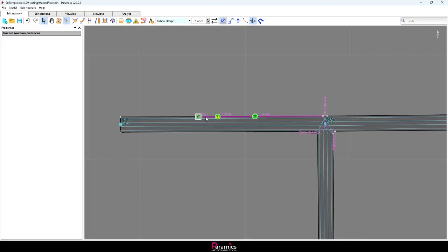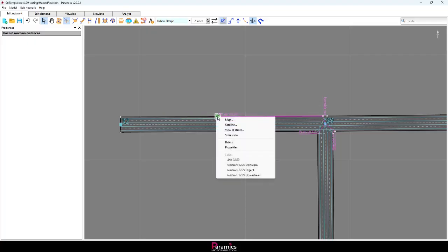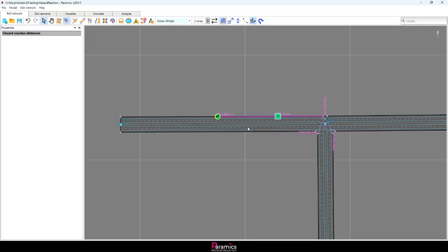This can lead to issues if they become overlapped. It may be confusing that when you pick the icon, it's unable to move. It will move in one direction, but not necessarily both. If they are overlapped and you can't grab the correct one, you can use the right-click feature to pick the appropriate handle, then drag that to the required location.